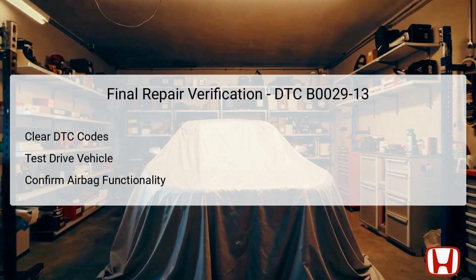After completing all troubleshooting steps, the final verification is crucial to ensure the problem has been resolved. Begin by using a diagnostic tool to clear the DTC codes from the SRS unit. After clearing, test drive the vehicle to ensure no reoccurrence of the DTC. During this drive, you should check that the airbag warning light is no longer illuminated, indicating a properly functioning system.